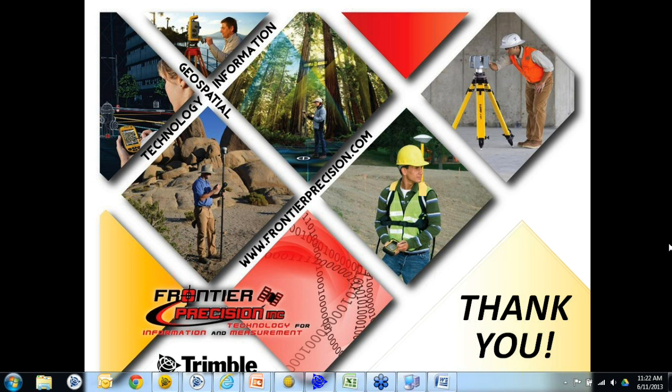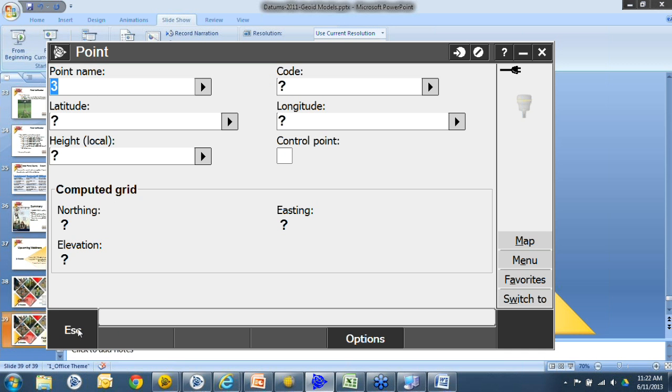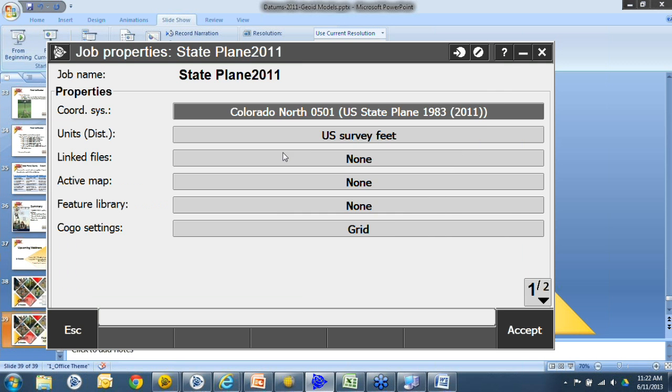Yeah, go ahead, Mel. Hey, one of the questions that seems to be most popular coming in right now, and I think we should clarify, is when we use the term today of NAD83 CONUS, some questions are coming in saying, well, NGS never published anything that's called NAD83 CONUS. Right. And you're correct. If you looked at a data sheet, it would maybe say NAD83 and an epoch date of 1991.35.